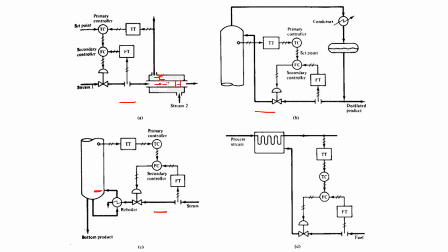So for that, first I have to measure this, and that is compared with the temperature controller, and it decides the output that becomes the set point. So before you control it, first you measure the current flow rate and make it ready for the master controller. So the current flow rate of this stream, because this is the manipulated variable. Before it acts on this manipulated variable, the other parameter which is closely associated with this is the flow rate of this stream one. So measure the flow rate, and this is the set point, and this is the procedure. Take control action. Then if you give this, automatically you can reach this desired point. So this is how it works.